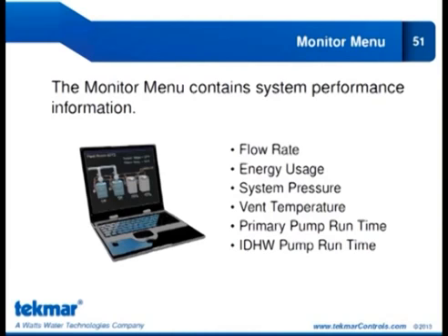The one thing that is important, as I mentioned, is there are two types of flow meters in the market. One is the pulse type. They're actually a digital signal, which we then interpret based on pulses. We're not compatible with that. We're compatible only with the Vortex style, which takes the analog input. So if they have one, by all means, we could definitely take a look at that and potentially support it, because right now we just want to make it easy to set up. Based on all the different models that Grundfos carries, once they know what model they have, they select their model, and it maps the actual trip points, the rails. But by all means, if there are other ones on the marketplace.